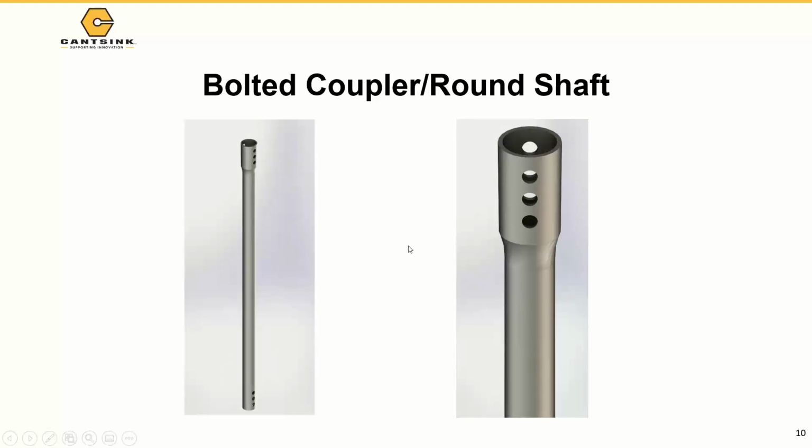Most of these shaft sizes, especially for the people who have an ICC-ES report, when you go to that report, you have these specs for these helical piles. You will see what the rated torque is. That means the maximum torque that you can use to install that shaft into the ground. So they have rated shaft torque. They have also rated capacity because they have been tested. And you will see the max torque that the pile can be installed to.